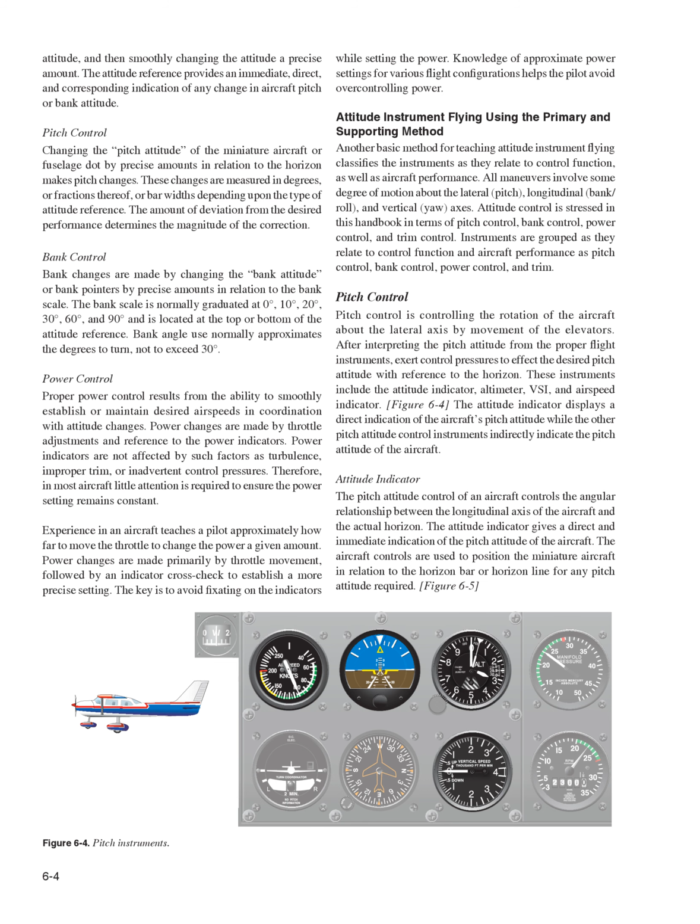The bank scale is normally graduated at 0 degrees, 10 degrees, 20 degrees, 30 degrees, 60 degrees, and 90 degrees, and is located at the top or bottom of the attitude reference. Bank angle use normally approximates the degrees to turn, not to exceed 30 degrees.